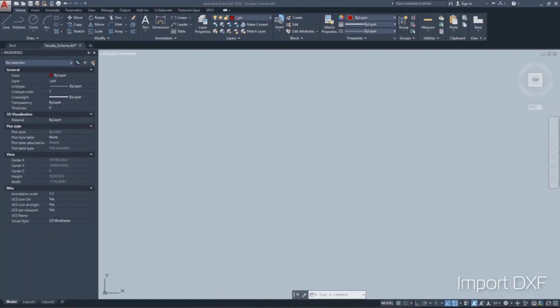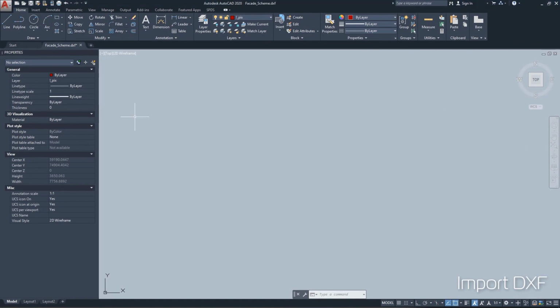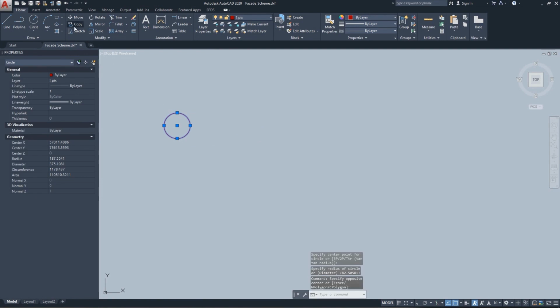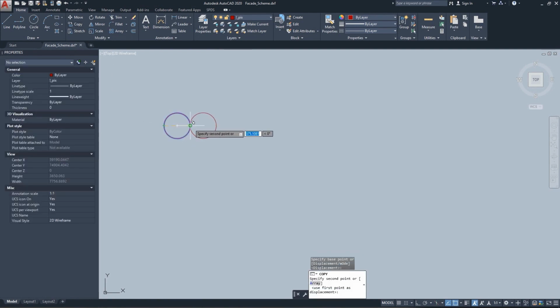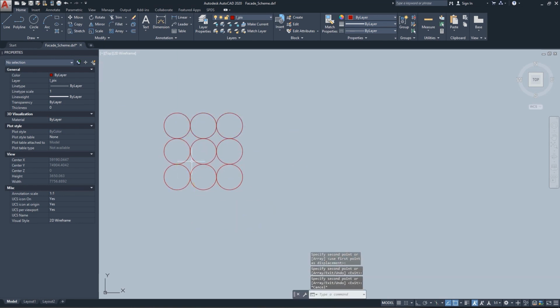It is important to import DXF files. The principle here is as follows. In AutoCAD or any other program that supports DXF, you need to create circles at pixel locations. Connect the circles sequentially with segments from the initial to the subsequent. Furthermore, use segments, not a polyline. In line with this order in Lightstream, pixels will be built.